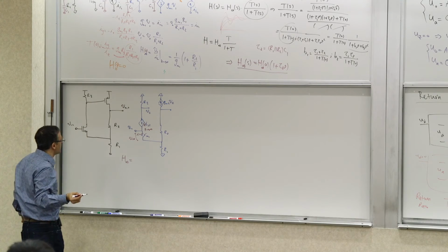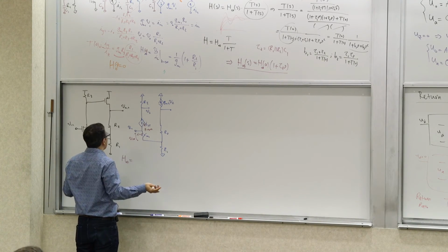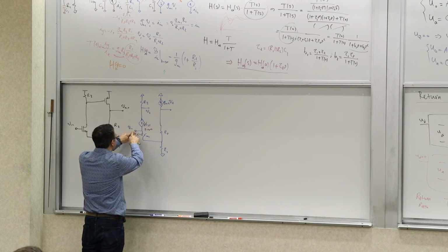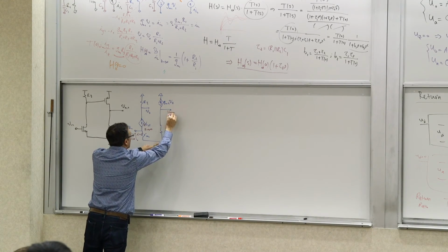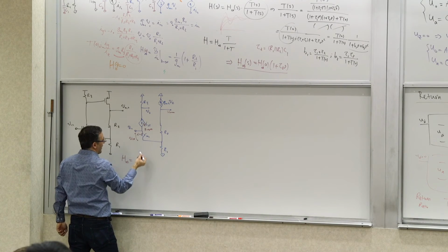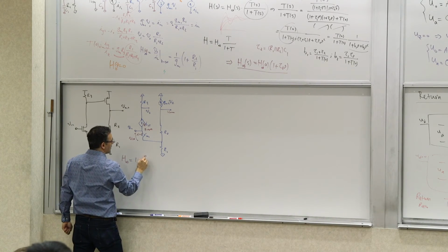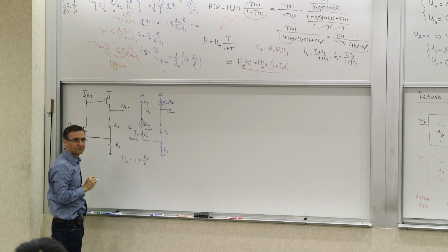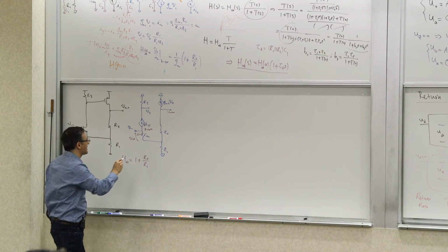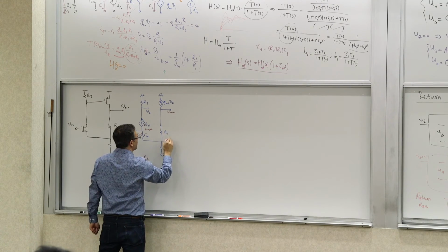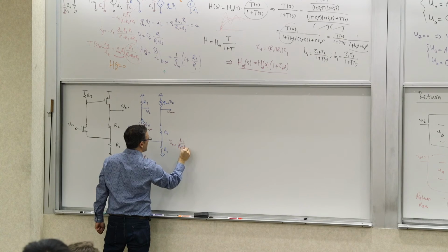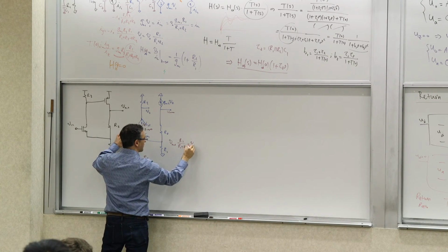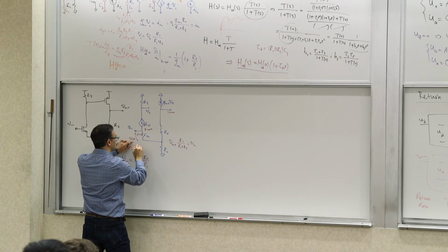That was the asymptotic equality principle, right? It came from that. If k is infinity, this voltage has to be the same as the voltage from V out through the division ratio. This division ratio is V out times R1 over R1 plus R2, and because of the asymptotic equality, that equals V in.